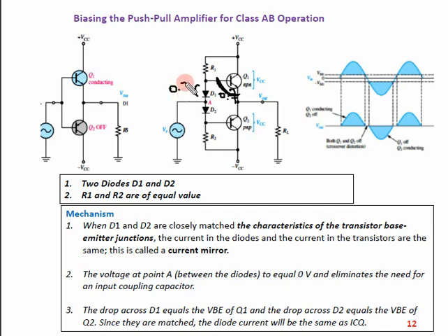So this configuration is going to bias or conduct this base-emitter junction for this period of time, and similarly it can be explained for this part, which is PNP. This combination of R1 and D1 is going to rectify the crossover distortion somewhere over here, for this positive half to be very precise.